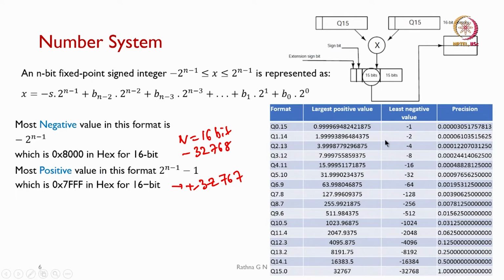As we know, we need high precision for most of our speech or audio processing. So, the Q15 format is what we will be using in our application, and we know that the multiplication is going to produce 30 bits, because both inputs are in Q15 format, that is, 16-bit memory that I have taken.